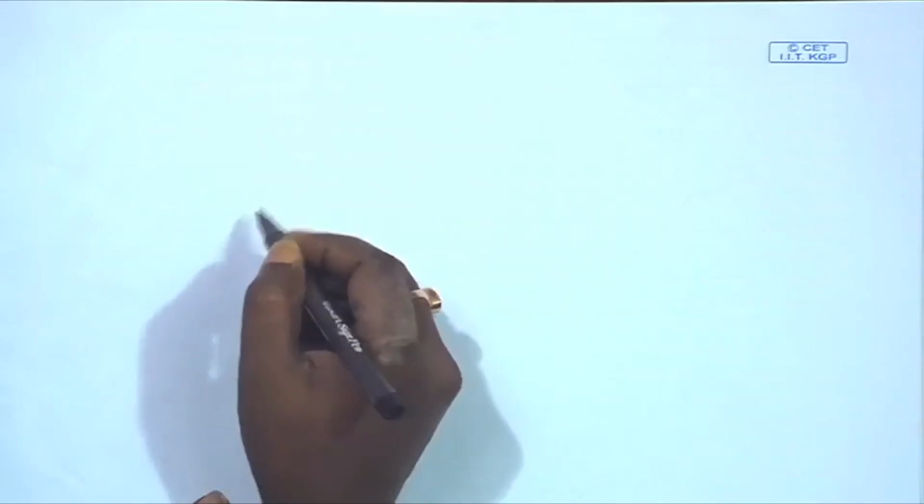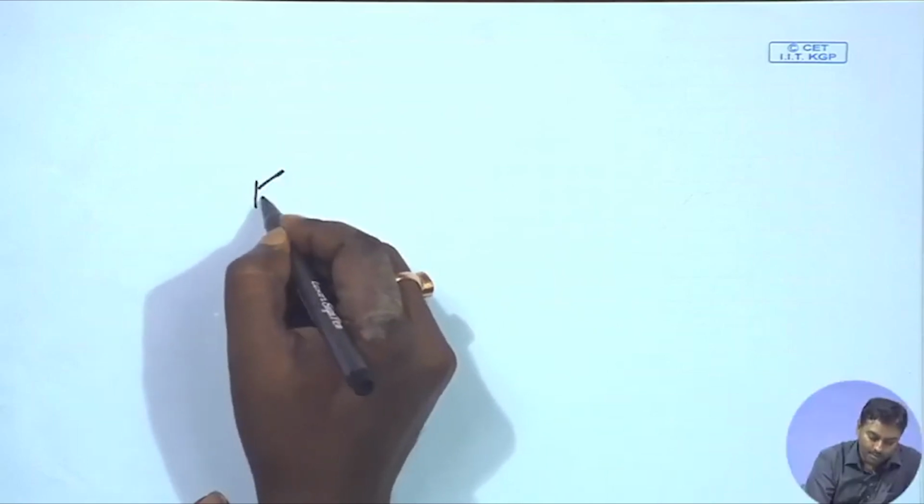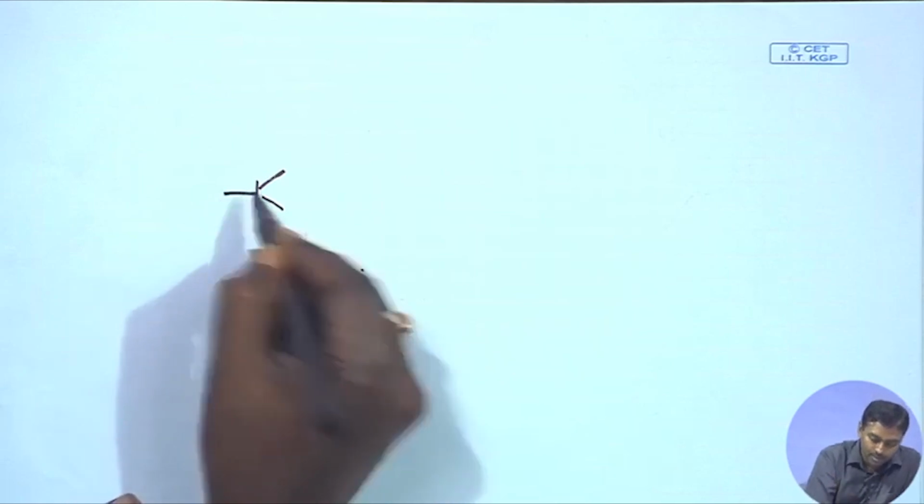Okay. So, let us try to see what we actually employ as a circuit for pulse amplitude modulation. Let us say we want to do natural sampling, because we have already seen some advantage of natural sampling. What we can do is take a switch. It can be a transistor switch or a MOS switch, whichever switch you have.